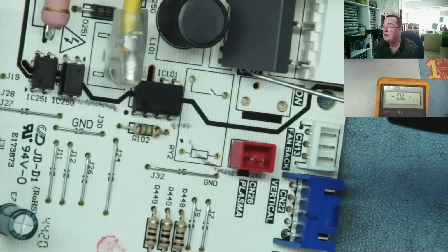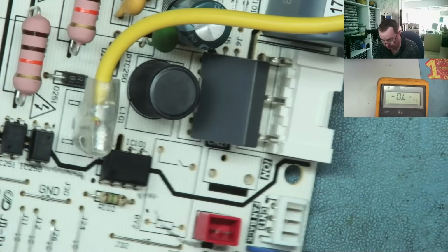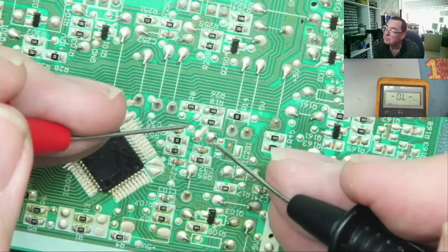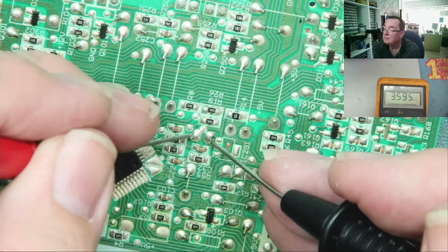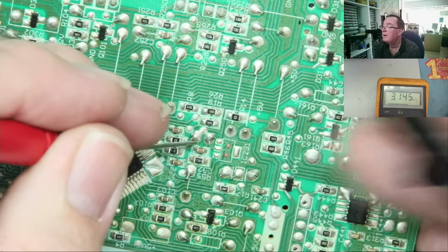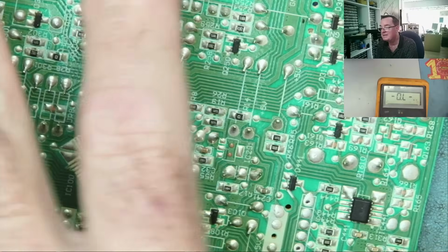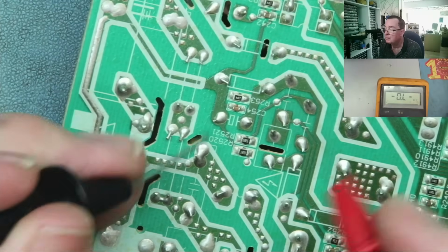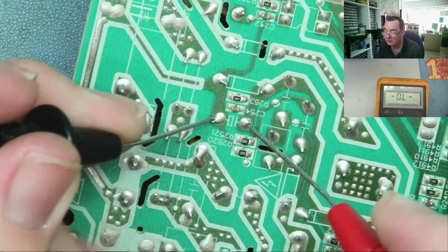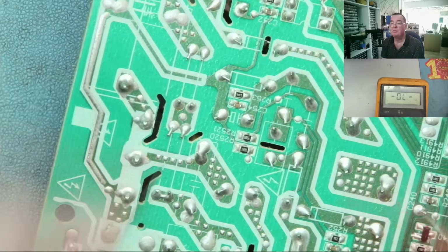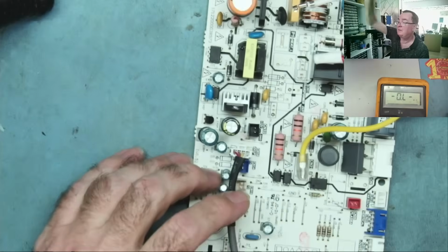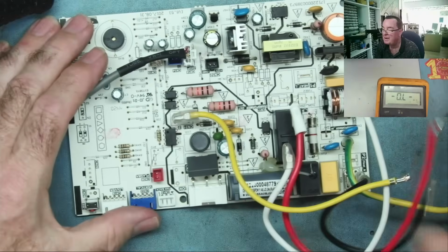There's one down here and one up there. Okay, so I just thought a joint looked like a bad joint, but it doesn't. I mean, obviously you can look around at all the joints. I'm open to spotting something as I go around, because I'm looking around the board. I'm going to do this side anyway. Up here, over that way. Yeah, it's there. It's marked as a capacitor. No short. I'm not going to test all the little capacitors, probably because they don't tend to fail.